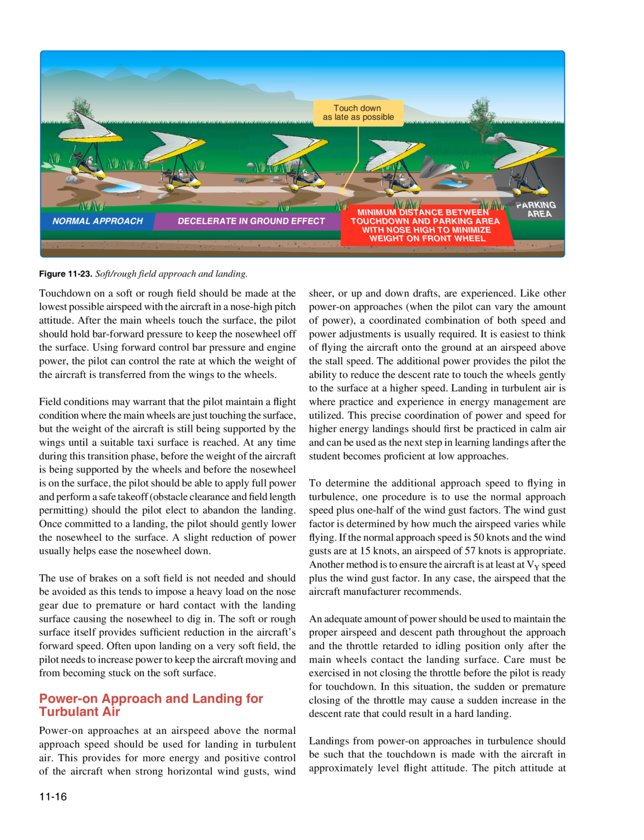The use of brakes on a soft field is not needed and should be avoided, as this tends to impose a heavy load on the nose gear due to premature or hard contact with the landing surface, causing the nose wheel to dig in. The soft or rough surface itself provides sufficient reduction in the aircraft's forward speed. Often upon landing on a very soft field, the pilot needs to increase power to keep the aircraft moving and from becoming stuck on the soft surface.